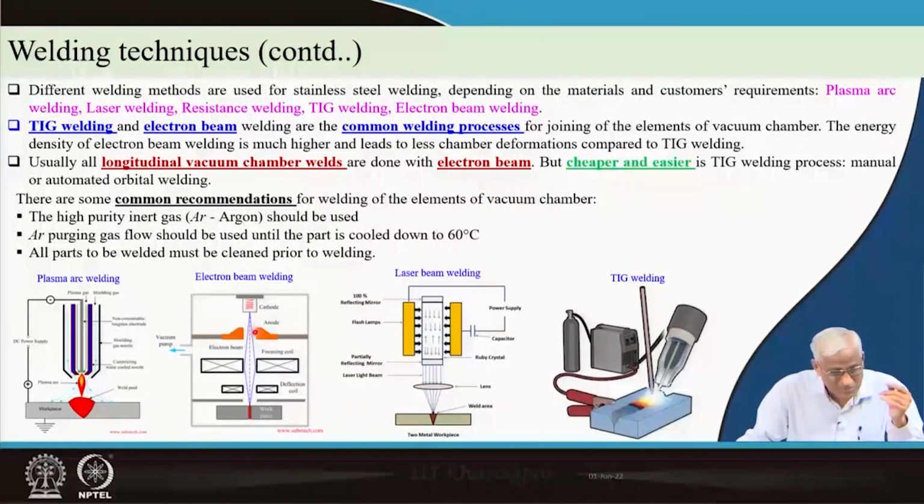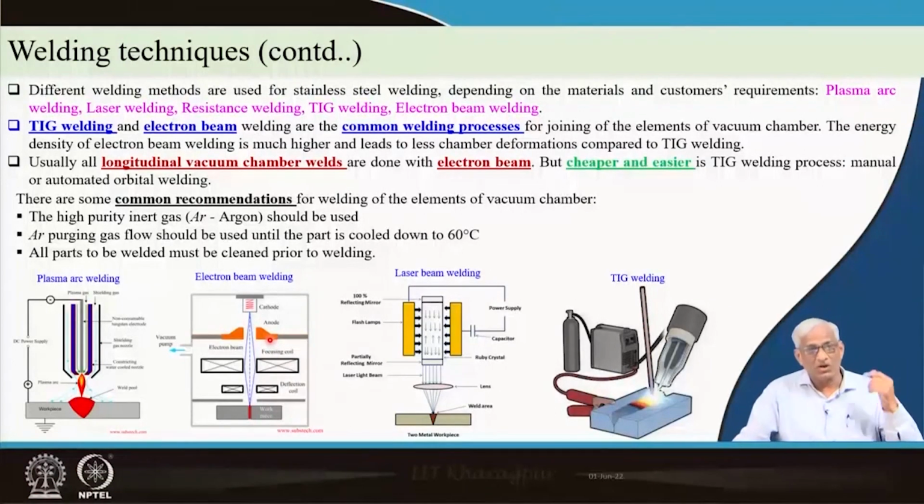So, these electron beams are first accelerated, and they are produced from thermionic emission or field emission, and they come towards the anode, and they get diffused. These are cathode ray beams, and they can be focused again by focusing coils, which are nothing but electromagnets. Because charged particles can be deflected or focused by suitable design of magnetic coils, you can control this focusing by changing the current through them.